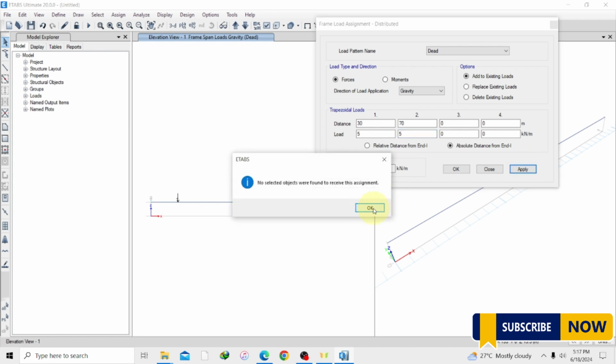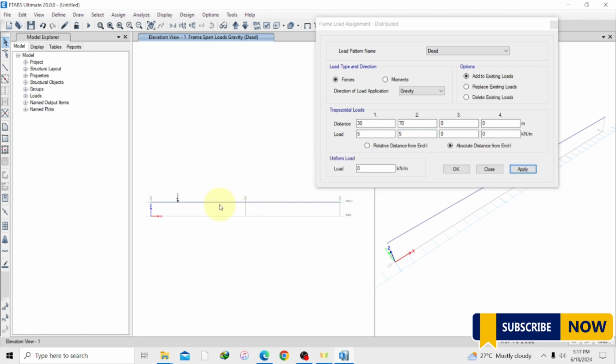Apply. Yes, first of all, before you apply the load, we all know that you are supposed to select the beam you are applying the load to. So once I've selected it, I can now apply to it, and then we have our UDL on our beam. So we click on OK.